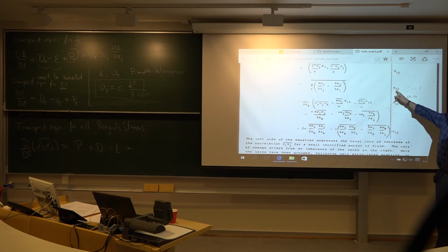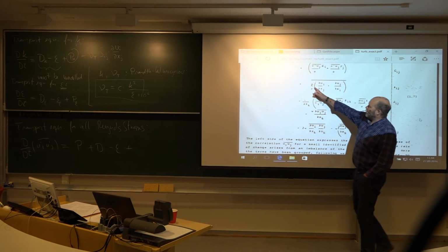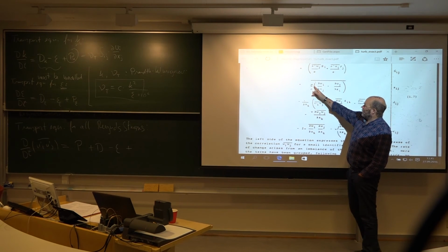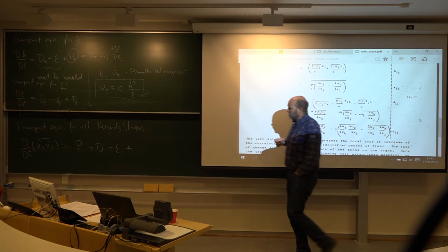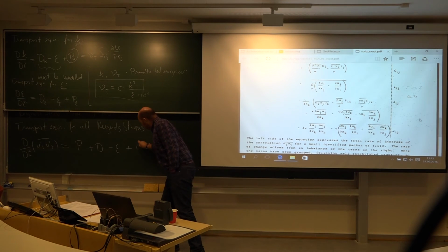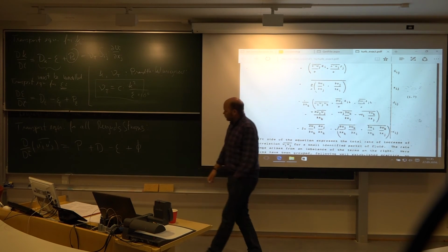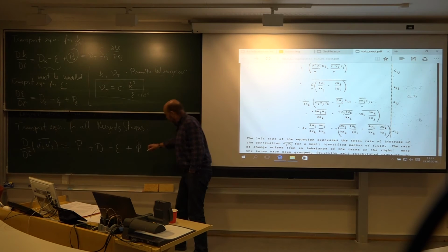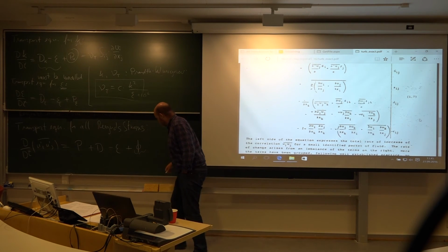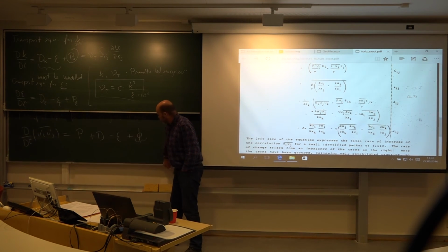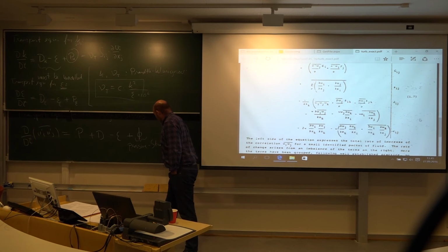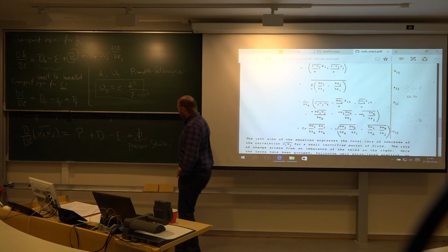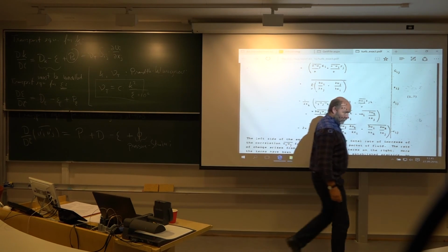This term is actually the pressure fluctuation multiplied with the gradient of the fluctuating part. We call it phi, and that is a new term. This one is now called pressure strain.